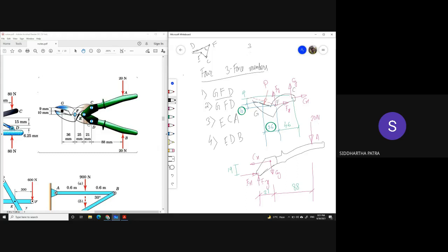But then when you switch to the other half, you have the force at G and at C. And at C, there are 2 components. But G you have already considered in the previous set. So you see there would be only 2 additional unknowns. So 5 unknowns, and then you can write the other 2 moment equations. So 4 equations and 5 unknowns.